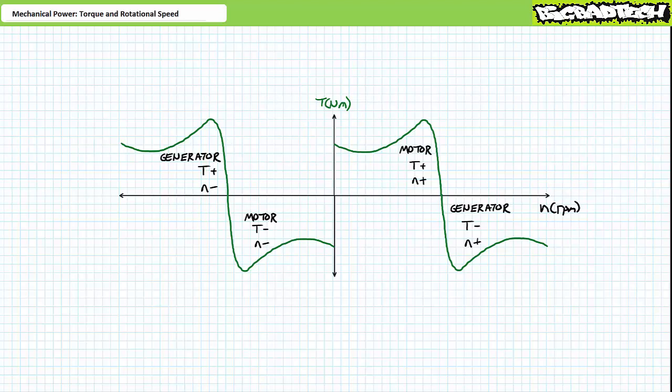You'll again recall the production of negative mechanical power is just a confusing way of saying consumption of positive mechanical power. This more holistic chart reveals something interesting about induction motors, where the term motor is in quotation marks. They're not motors. They are rotating electrical machines and can be used as motors or generators. Put that in your pipe and smoke it. If this is too much right now, relax and fear not. We will revisit this concept in much later lectures on asynchronous generators.